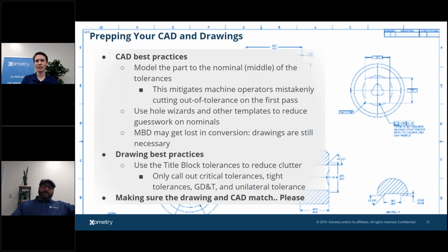Minor diameter, yeah. So if you make it to the minor diameter and you forget to give us tapped holes on your print, it's a good chance the machinist is going to recognize that hole diameter and question whether or not that should have been tapped. That's the other. Yeah, you see like what it was, like 0.214 all the time, and you kind of know that there's a tap feature there.